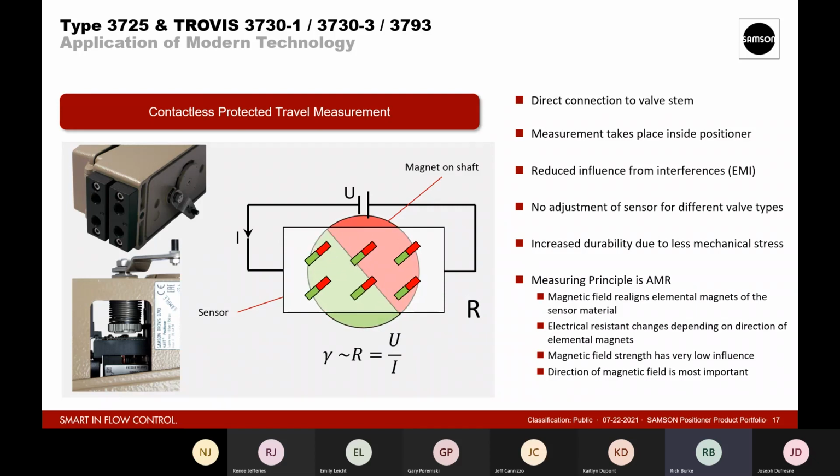We weren't aware that they had so much water hammer in these units. So they just decided as a general rule to go to 3793 to replace any positioner that they had, and those are on any new valve that they buy, just because of that. Then they found out that it's very easy to use and very intuitive, and they really like it. Besides that, they also like the fact that they don't need boosters on a lot of the larger actuators, and that for double acting, they don't need reversing amplifiers anymore because of the 2 outputs on the 3793.